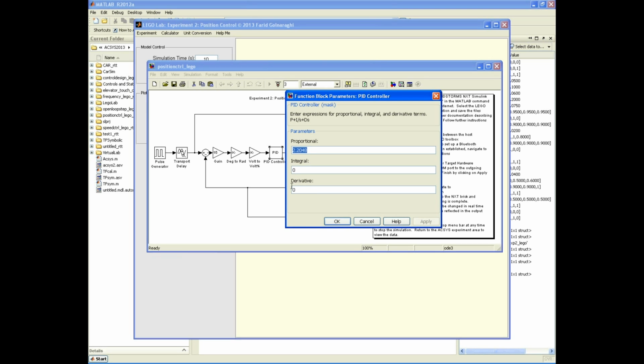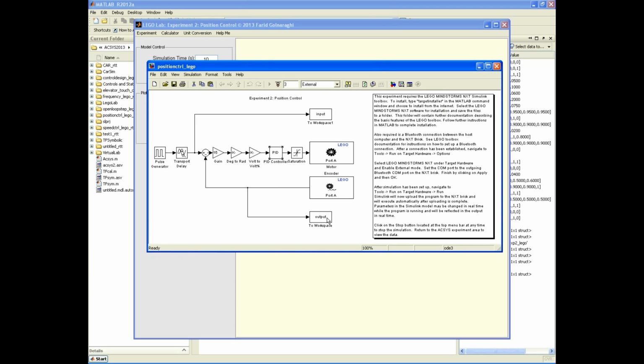The value of P equal to 2.2048 can be calculated through Matlab computation of the closed loop transfer function for this particular pendulum. Next is the saturation block, which is used to control the power percentage of the motor. The motor block then receives the instructions from the previous blocks and relays this into the NXT motor for actuation. The encoder block acts as the sensor of the system, constantly receiving a new angle and updating the system based on this new angle. A comparison is then made between the input blocks and the sensor block, and the result allows for an adjustment to the actuation controls.